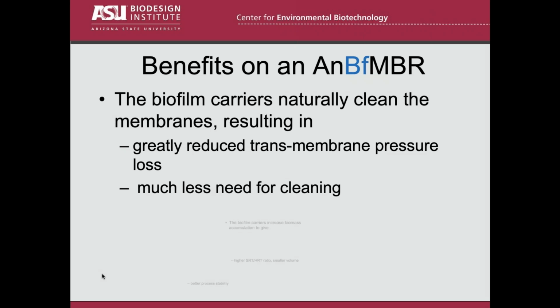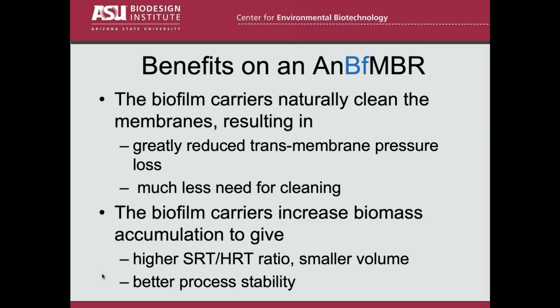Then giant benefit number two is that the biofilm carriers increase the biofilm accumulation. The membrane is already doing this, but when you put the biofilm carriers in, you then redouble the biomass accumulation benefit. So you can get really high ratios of SRT to HRT, and that translates into a smaller volume or a higher volumetric loading rate, and that translates into reduced capital costs.